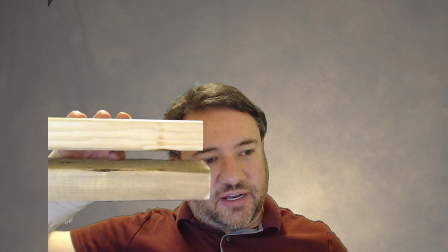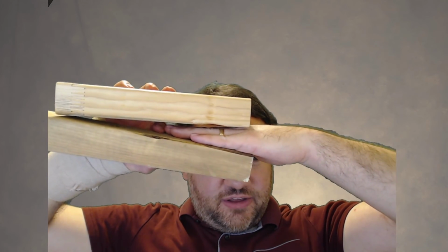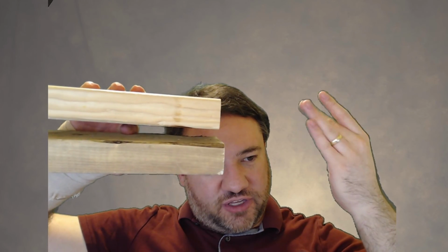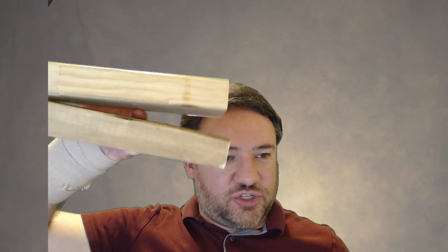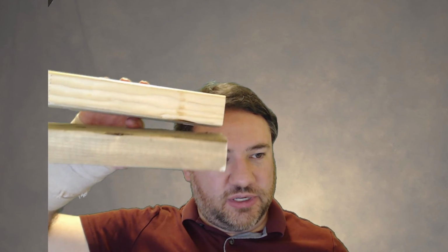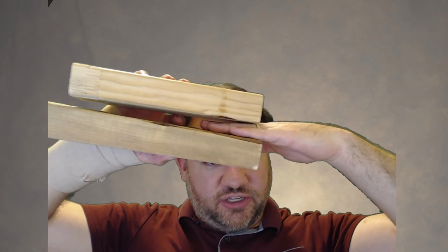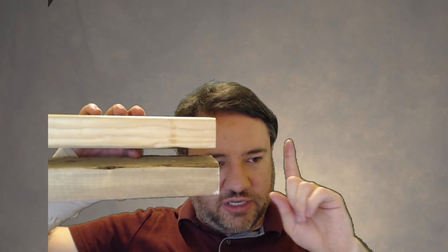So how am I going to know when the connection fails altogether? Either this one could fail in row shear, or these two together have to fail at the same time, so the sum of these two. If either of those things happen, then the connection is going to fail in row shear. Obviously my other option is that I could have a yielding failure, where I only have one yielding failure calculation for the whole connection, or I could fail in group tear out or net section, which we haven't talked about yet.